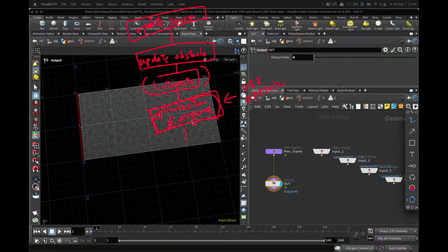Now next, after you have calculated the best value for the U and V for each grid to have the most balanced value in terms of the divergence, next you could advect the velocity and the smoke, meaning update the velocity and smoke value.